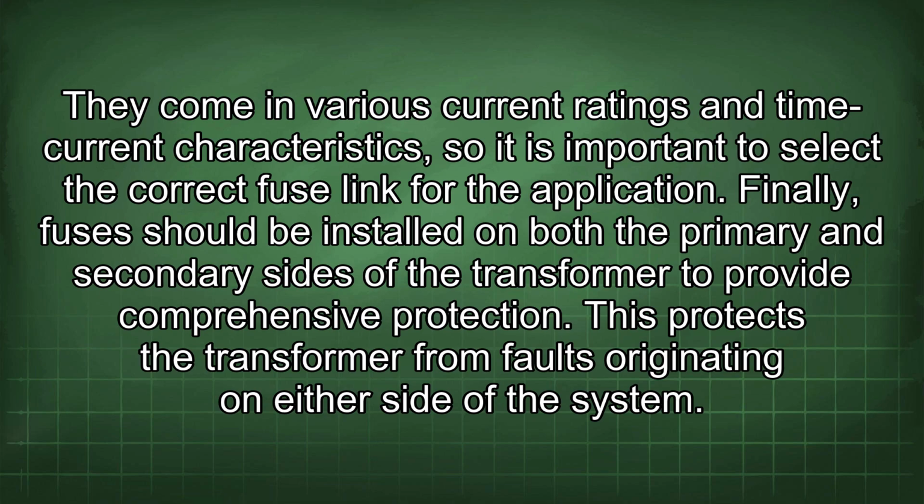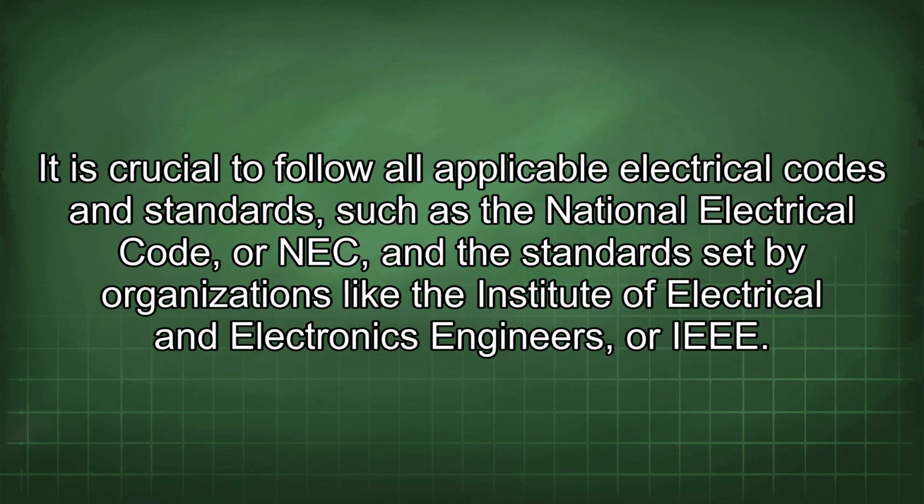Finally, fuses should be installed on both the primary and secondary sides of the transformer to provide comprehensive protection. This protects the transformer from faults originating on either side of the system. It is crucial to follow all applicable electrical codes and standards, such as the National Electrical Code, or NEC, and the standards set by organizations like the Institute of Electrical and Electronics Engineers, or IEEE.